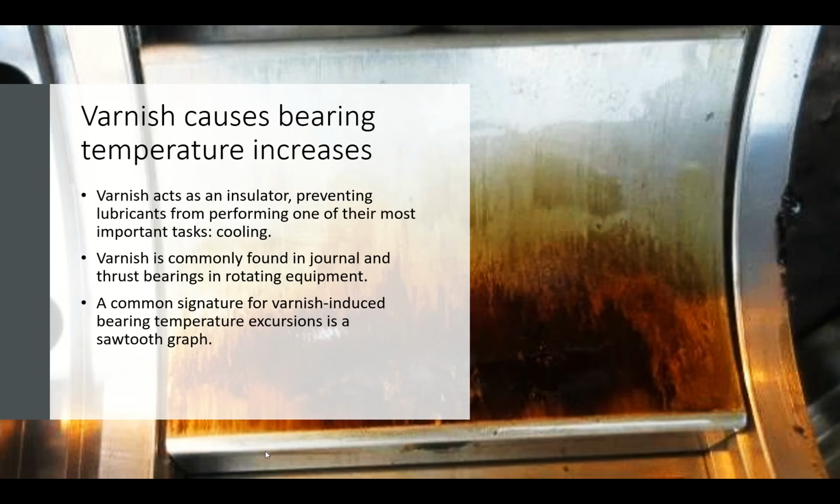The second typical phenomenon that we have been informed of in the field is that customers or end users are asking us and reporting abnormal temperature increases on their bearings, typically on industrial gas compressors, and we have been digging a little bit deeper to understand what is really causing this. And absolutely, if we talk about temperature increases, the first thing you think about is there must be an effect of lack of cooling. And as we all know, the number one function of lubricant is cooling, beside other functions, but cooling, dissipating the heat, is number one.